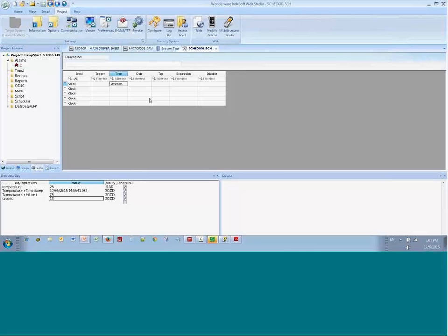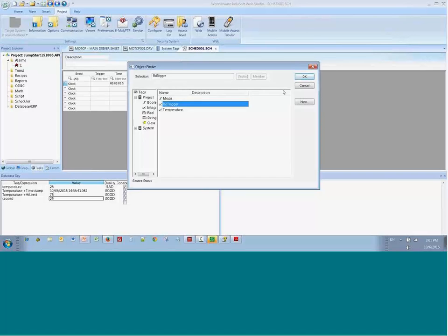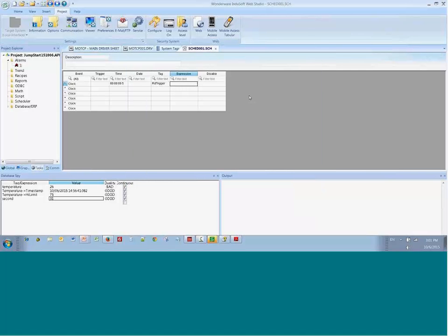So let's say that we wanted this every 100. 100 is a little fast. Let's say 500 milliseconds. I can just use 0.5. I don't use the date field, and I want to take that tag, and since I didn't remember what I typed, I'll go look here, RD trigger, and now every 500 milliseconds, maybe what I want to do is say not or invert the RD trigger.